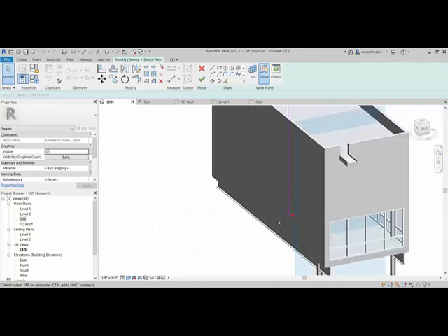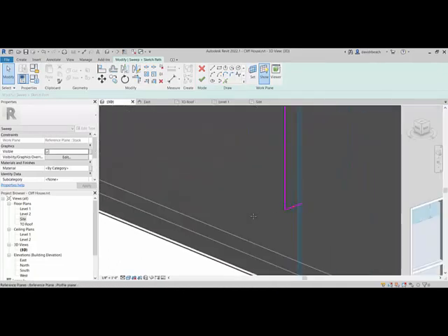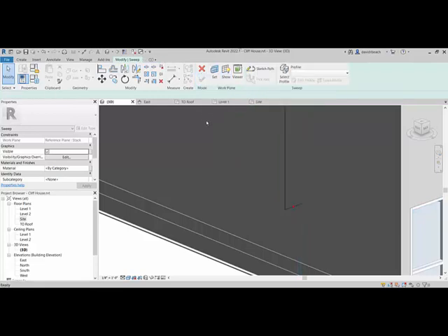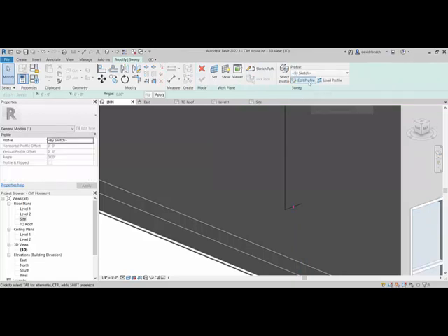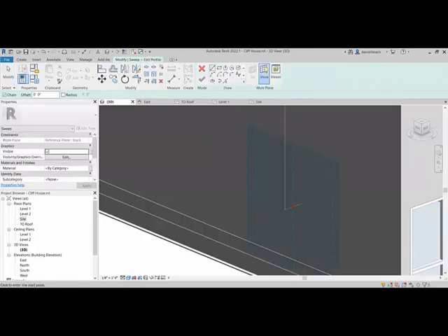And you know, those stack things, they're about 8 inches in diameter. So I'm going to select a circle. Oh, actually, I need to go ahead and green checkbox. Right, my path is established. So green checkbox to establish the path. And now I need to edit my profile.